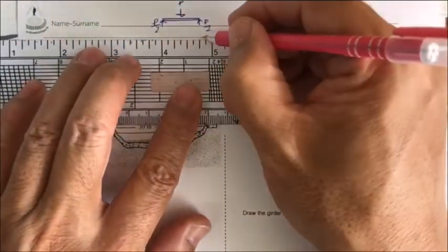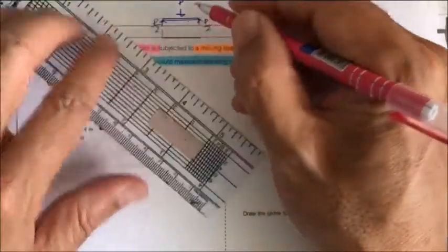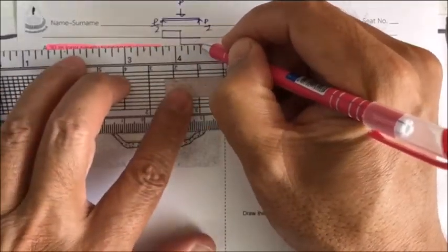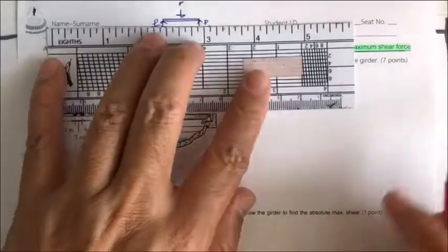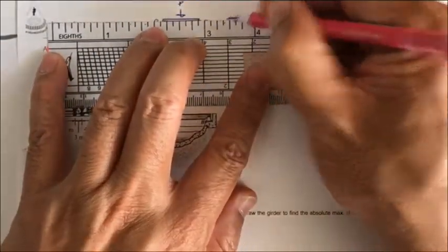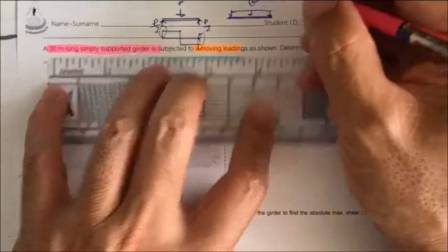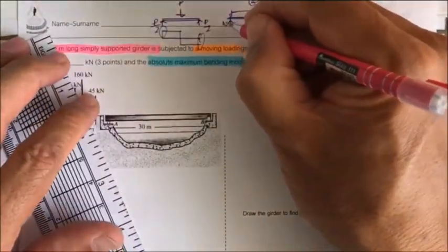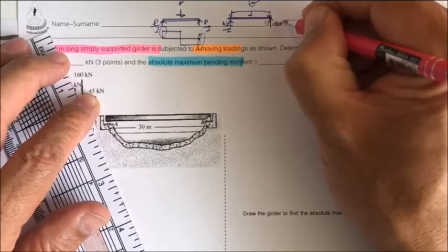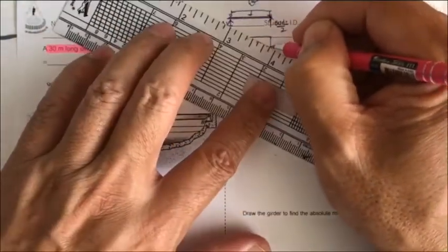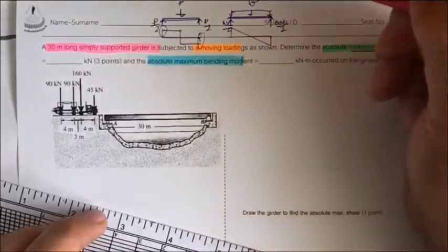If you draw the shear diagram of this beam, you may see that the maximum shear force occurs at the support. And if you change this to a uniformly distributed load W, you may see that we have WL over 2, with the span over 2, and the maximum shear force will occur at the support again. So most of the time the maximum shear force occurs at the support.